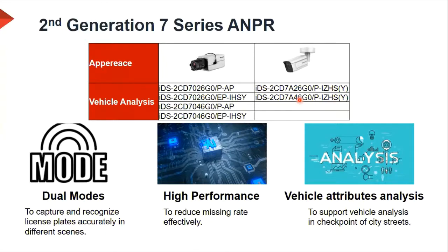The other thing is that the box type camera also comes in a housing. The box type with a housing also has IR, with similar IR distances, but the lenses are slightly different. I think the longest lens on this one is 11 to 40 millimeters, which will go a little bit further than this one over here. But I would say nothing more than about 45 meters away where your number plate should be. The same specs apply, where you need to stick within your 30 degrees.